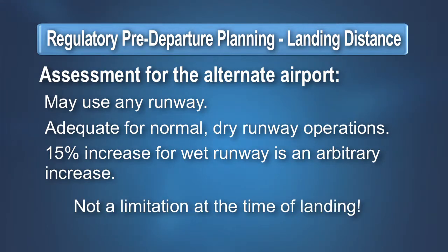The factored landing distance calculated during pre-departure planning is not a limitation at the actual time of landing. A runway may be used for landing when the factored landing distance exceeds the landing distance available published for that runway. However, an assessment of actual landing distance is recommended. More on that subject in a moment.